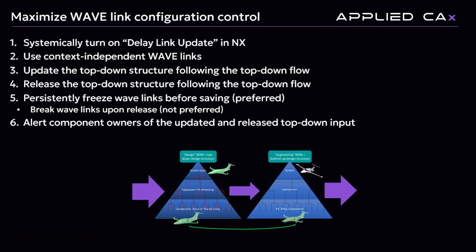This is a big load on the system, because depending on how many levels the position is away from that part, it's got to open and look through all those levels and get that positional data. And it also means if you don't open enough, you might not be up to date. By making it independent, you don't have to worry about that. You have the geometry up to date, but the position is locally defined.